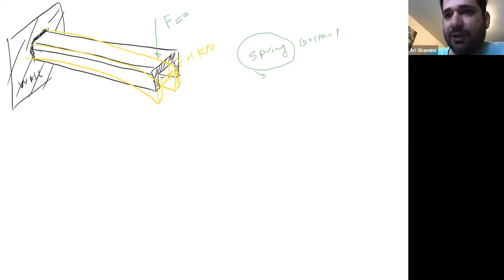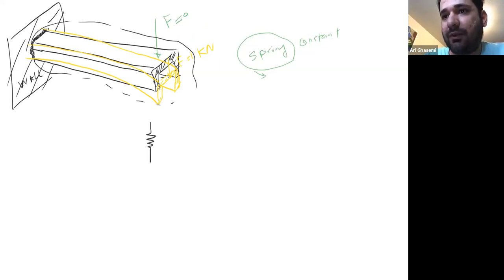That is exactly the same analogy as a simple spring. Let's say here we have a spring instead of this part. Let's say I replace that system with the analogy of a spring-mass, and then you put F here. When F is 0, you don't have deformation. Then when you have 1K, this is going to get compressed. Do you see that? F is equal to 1K. And then you have some sort of deflection, delta.